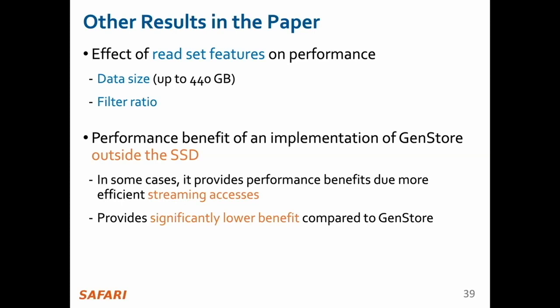For some cases where the read mapping is super fast, these larger data sizes might incur some overhead, but these designs are tailored for inside the SSD, which would enable us to stream through these large data sizes very efficiently. So then we conclude that in high performance read mapping systems, it becomes increasingly critical to devise a storage solution to benefit from the filtering process.